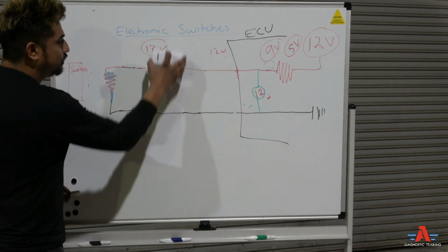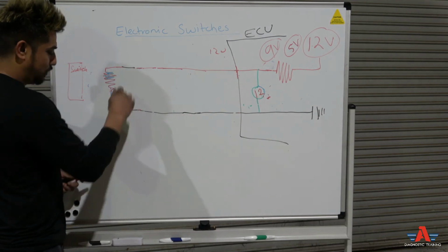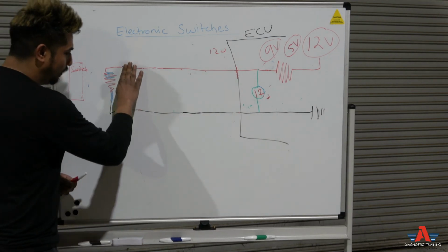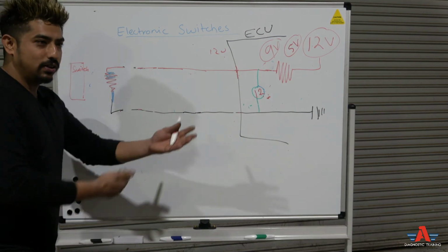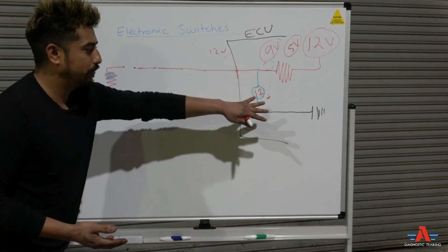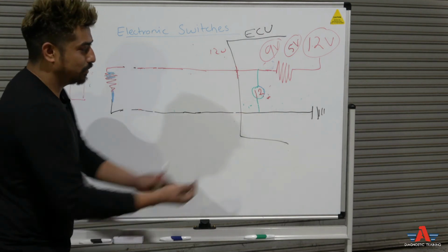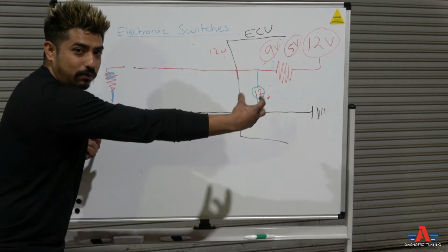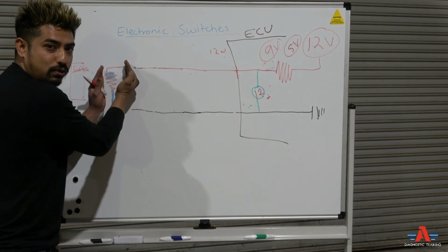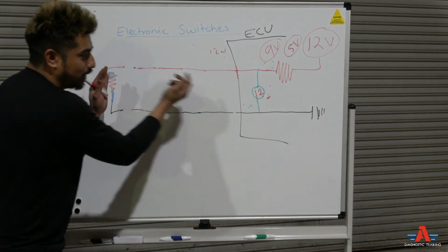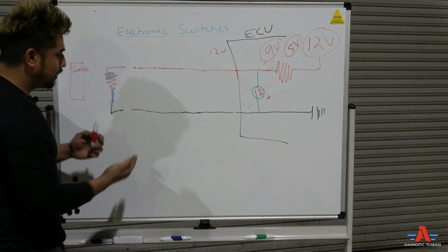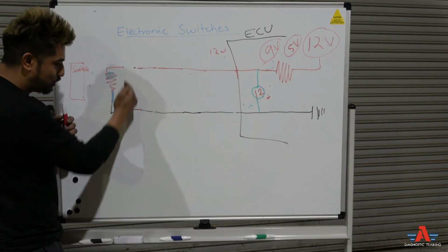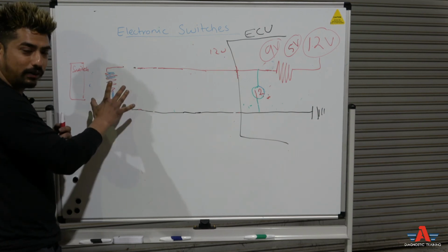Now if that happens, and as soon as you unplug this, the fault code changed to now shorted to battery, right? Because it was 0 volt here. As soon as you unplugged it, you fixed the short. Now it jumped to 12 volt, and the fault code description changes, means the switch is the problem. It's shorting that circuit to ground.